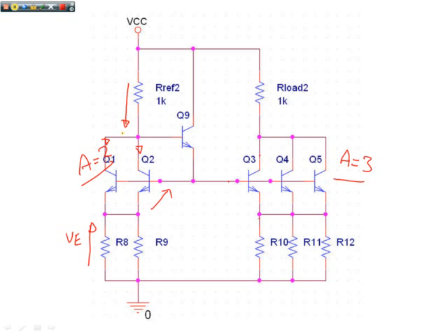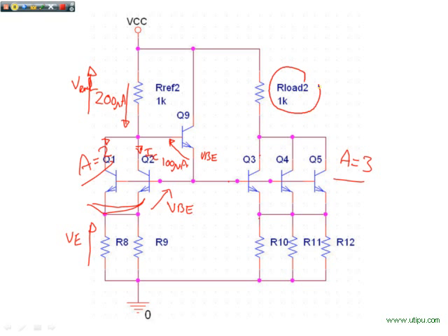VBE is proportional to the individual currents, so whatever the reference current is divided by the number of transistors. In this case we have 200 microamps. Therefore inside IC, for all purposes, we use 100 microamps. So you can now calculate VBE across this compound transistor. You would perform the same functions as we've done before, but now you're counting base currents on 100 microamps on all BJTs, and you would be able to calculate this value here, this volt drop. And we know the current here, so you now calculate this volt drop. So it's exactly the same design process.